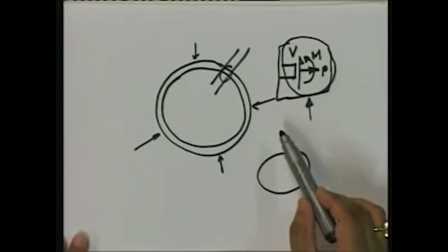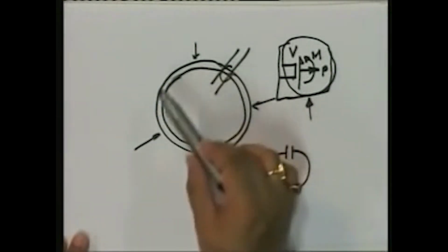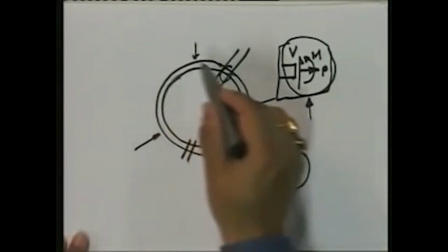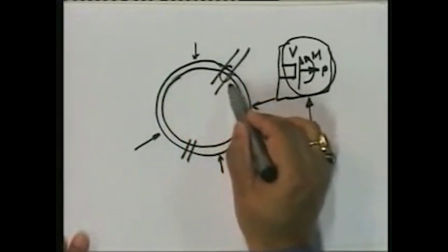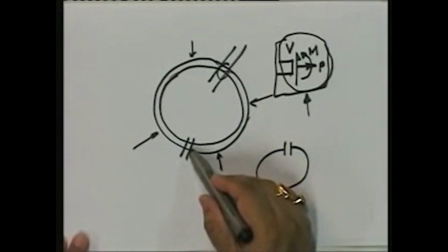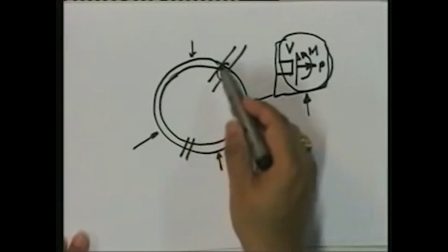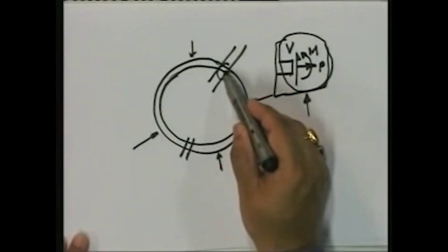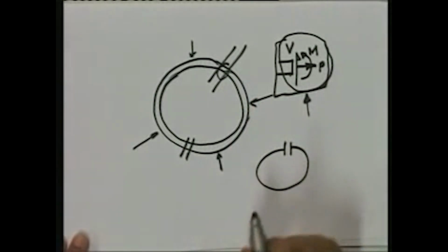Think about it. Take any free body that you wish to. This entire body is a free body, and we can make two cuts and separate out another free body. This is a free body. So is this. Every time I make a cut, how many forces do I release? 3. So if I make a cut and take this free body, I have 3 unknown forces here and 3 unknown forces here. So how many forces do I have? 6.